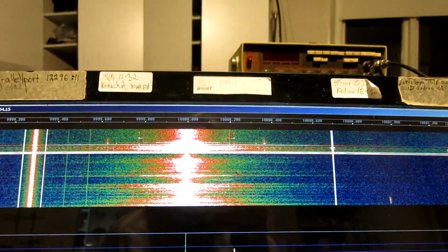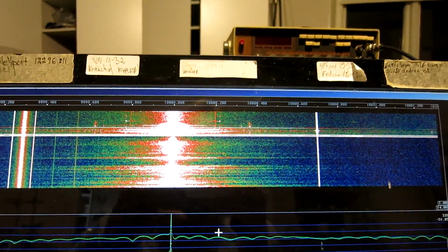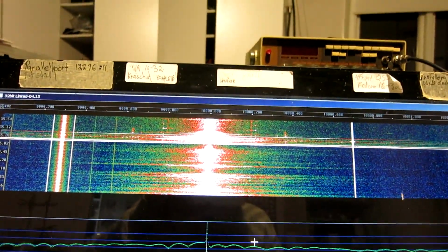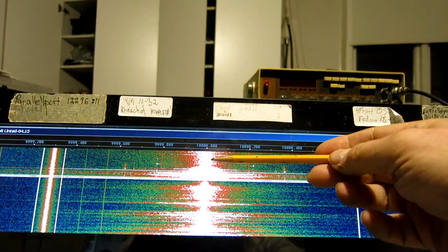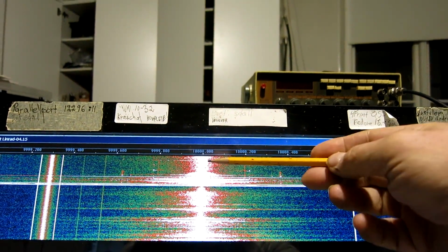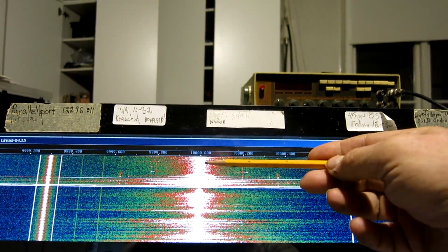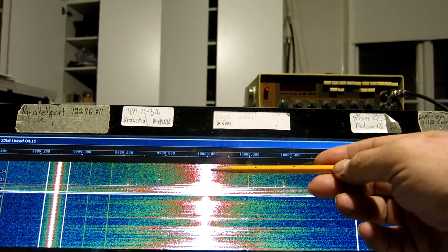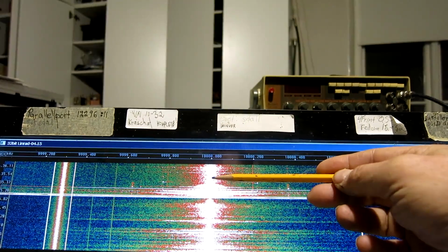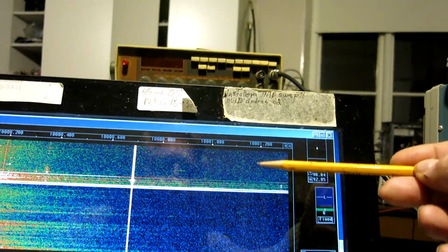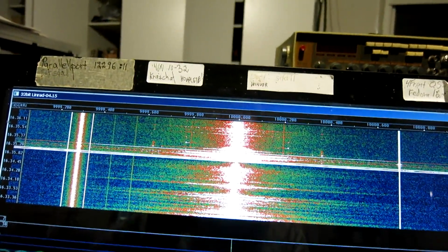I have now set the attenuator to 3 dB. Note that the strength of the sidebands is the same as before, or even a little better. It means that in dBc per hertz it is now 21 dB better. But at large separations we see some noise. So this is a bad crystal.